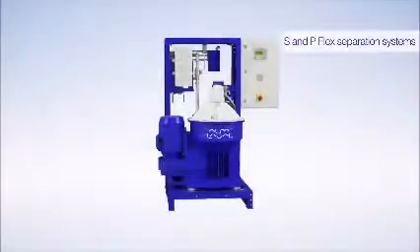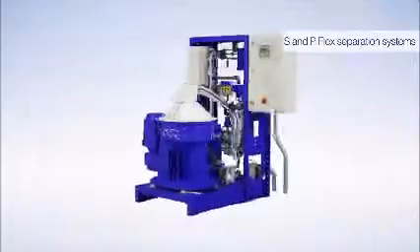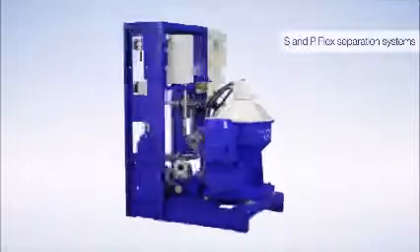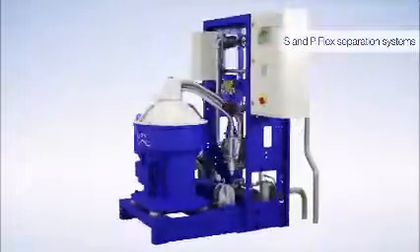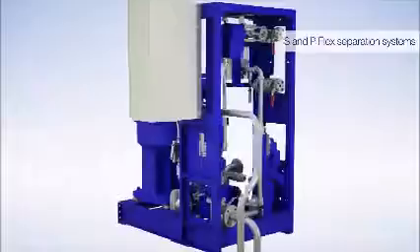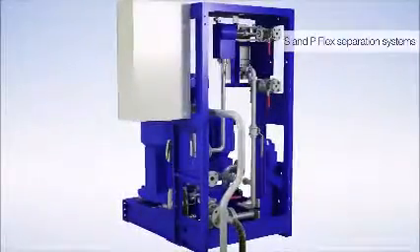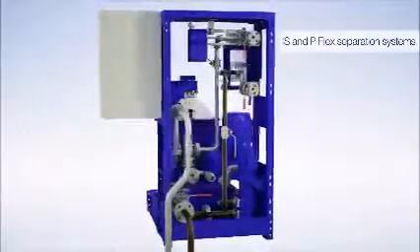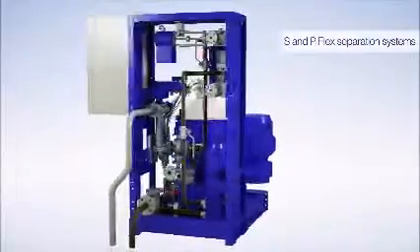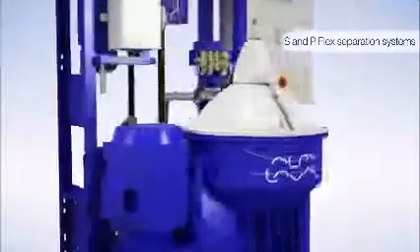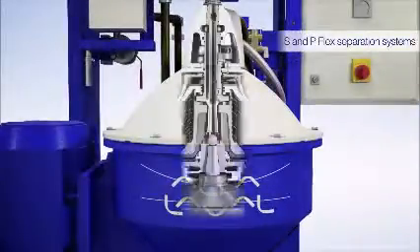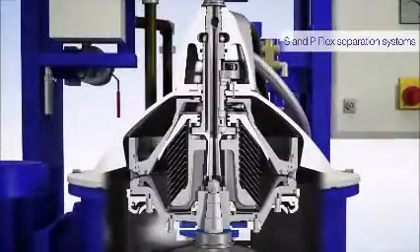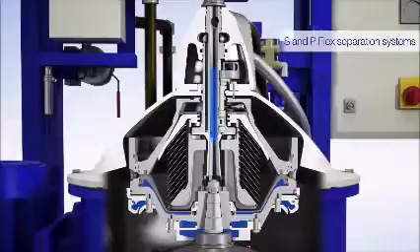Centrifugal force is the fundamental operating principle used in the purification of fluid. Centrifugal force is that force exerted on a body or substance by rotation. It impels the body or substance outward from the axis of rotation. Essentially, a centrifugal purifier is a container rotated at high speed. As it rotates, contaminated lube oil is forced through and rotates with the container. Only materials that are in the oil are separated by the centrifugal force.